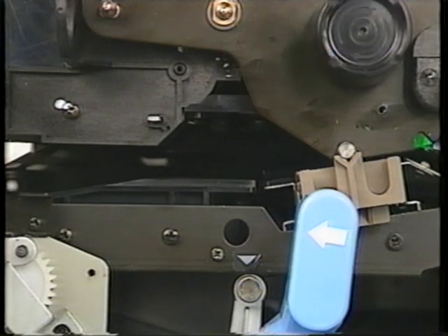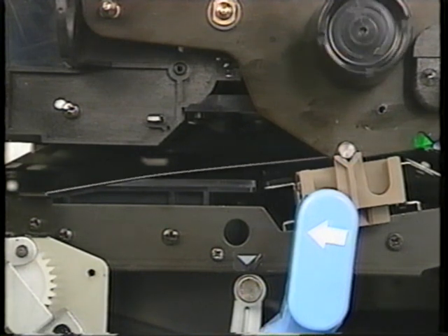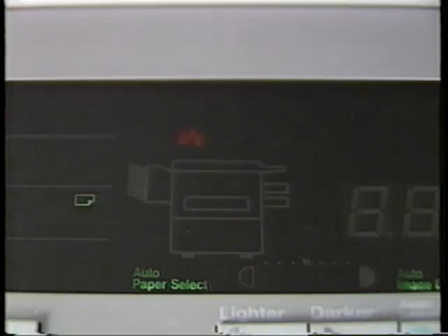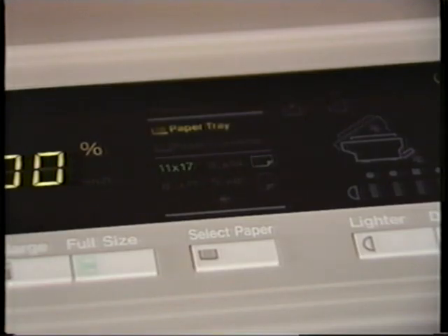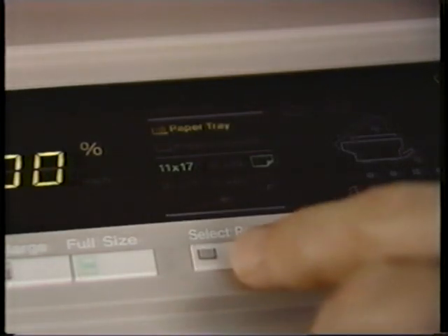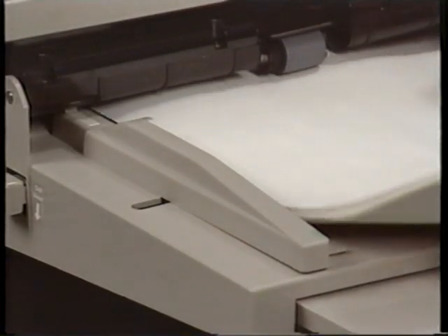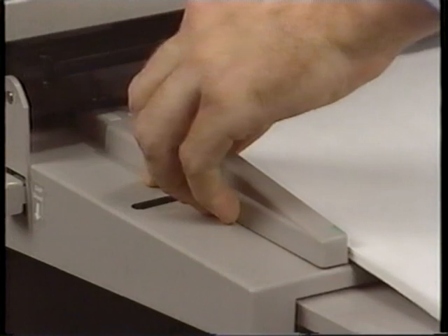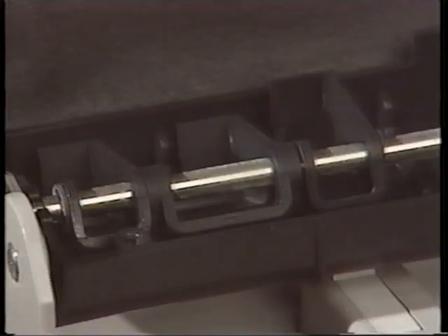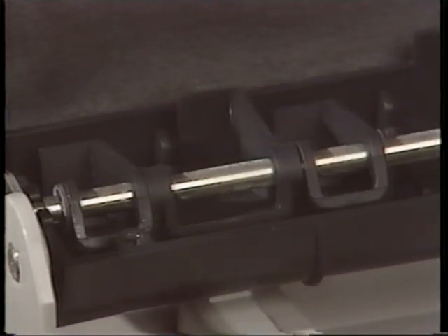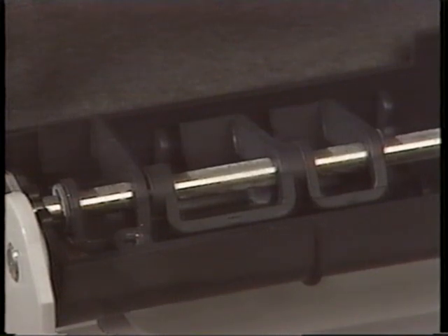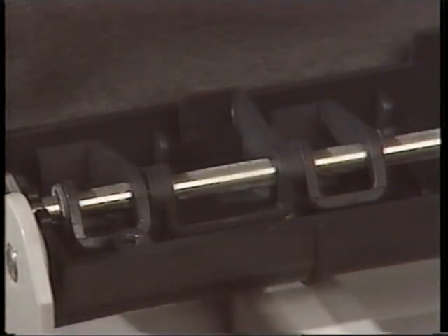If a sensor detects that a sheet has remained in one spot for too long, the control system knows there's a problem and indicates a misfeed. Other sensors tell the control system what size paper is being used. Sometimes they detect the position of adjustable fences in the paper supply. As the fences are adjusted for a certain width and length of paper, a corresponding sensor is triggered.